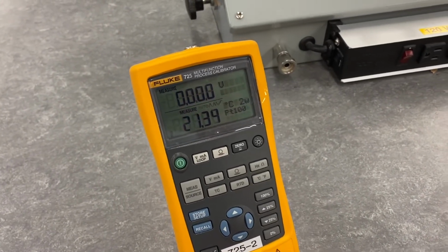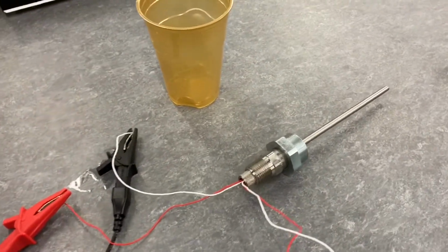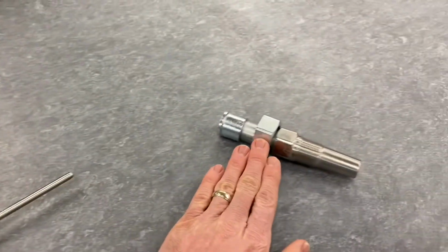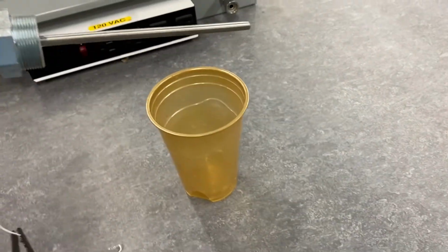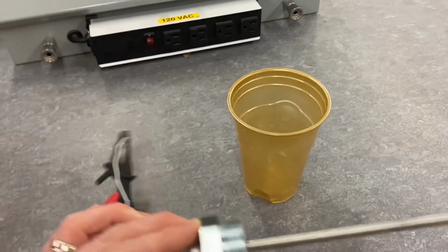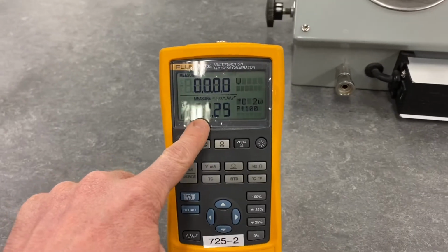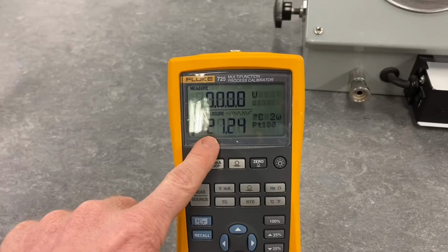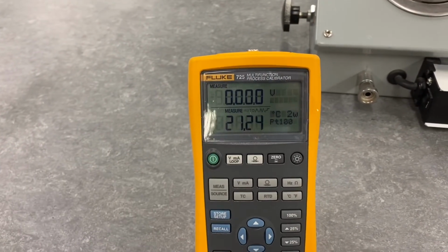There's probably a slight error due to lead wire resistance, but in this last experiment, what we want to do is compare the response time of the RTD when it is not in the protective thermowell and when it is. So we're going to be using our ice bath. We're going to be dropping this in, and we're going to be recording every few seconds until this drops down to 0 degrees in our ice bath. I don't have an ice bath in here right now, but that's what we'll be using, a cup with an ice bath in it. We're going to keep recording until it drops down to 0 and is stable.